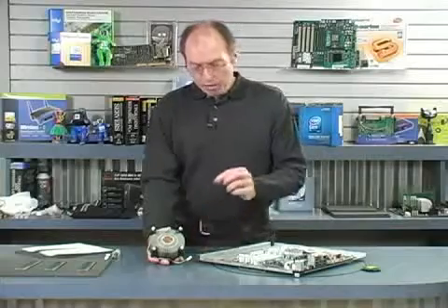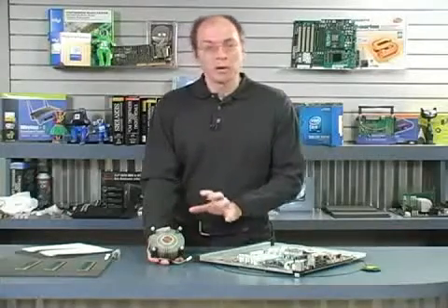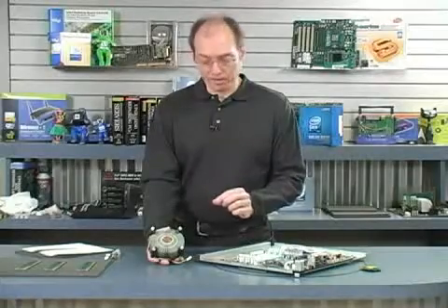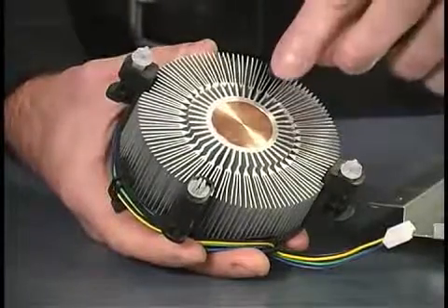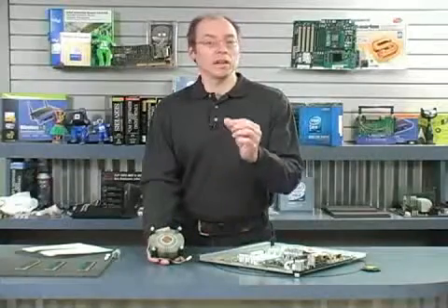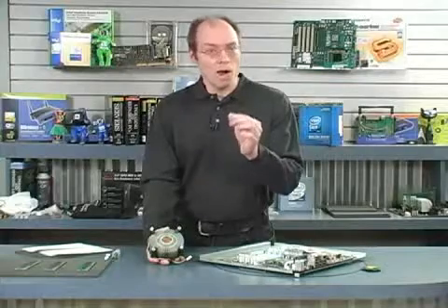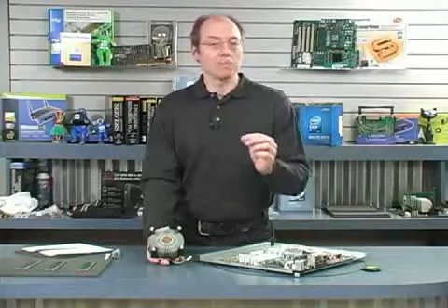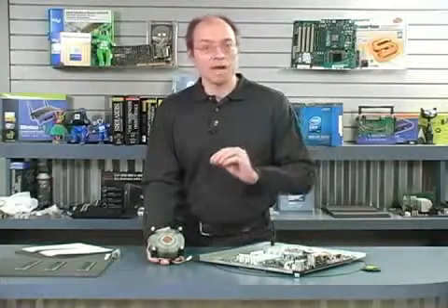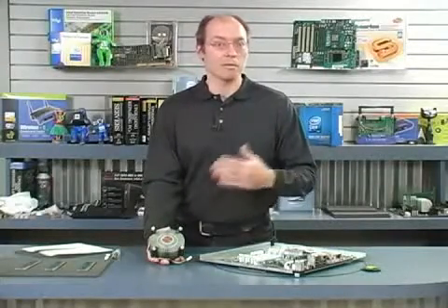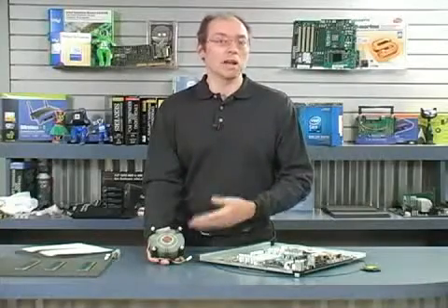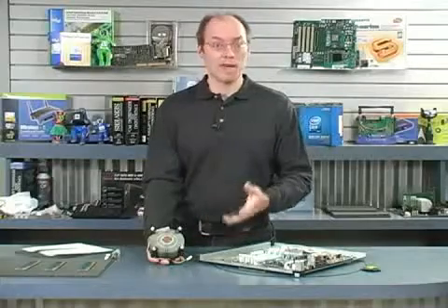Now, in addition to talking about that, we need to talk about what's called the thermal interface material. That's the material that basically has to go between the processor and the heatsink. The thermal interface material is basically a grease or a wax type substance that makes sure there are no little tiny air gaps, so that the maximum amount of heat is transferred from the top of the processor to the heatsink. If you don't use the thermal interface material, you're compromising the performance of the heatsink dramatically.